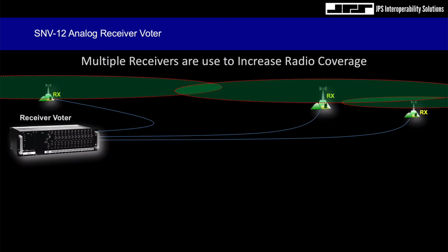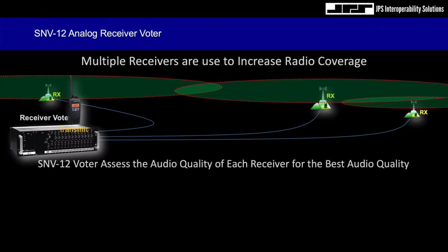And architecturally speaking, there are lots of variations of voter receiver systems, such as duplex, simplex, multicast, simulcast systems, as well as transmitter steering. But in any case, the use of multiple receiver sites is the basis of the implementation of the voter and comparator. As a subscriber unit moves throughout the region, hopefully its transmissions will be captured by one of the satellite receivers, and in most cases, the transmission from the subscriber unit will be received by more than one receiver, and this is a good thing.